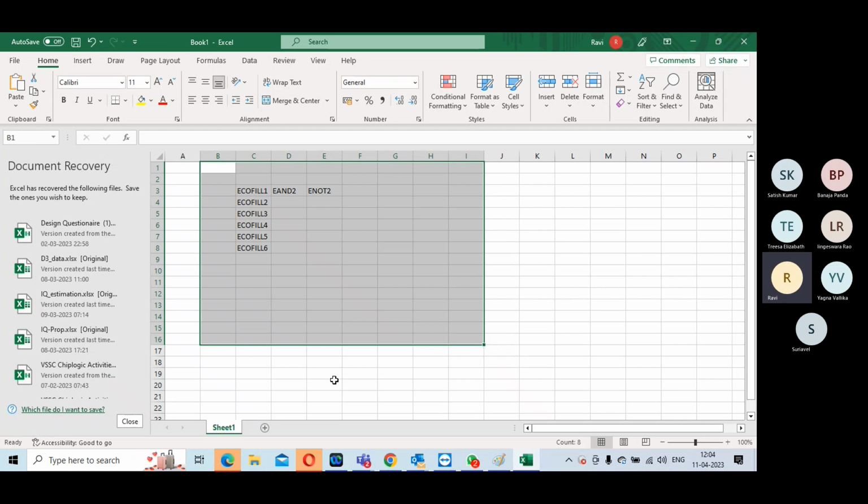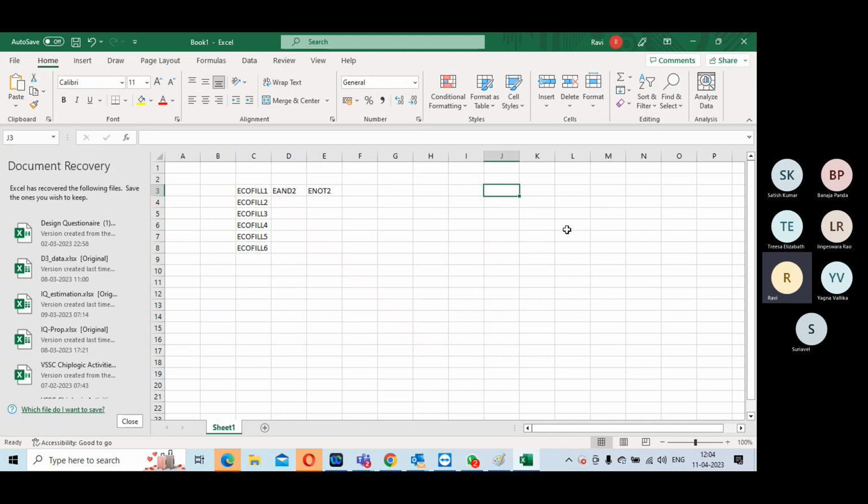The map file, what you are actually understanding as the map file, is different. That is a GDS map file, which tells you what the M1 layer actually means, that it is layer 23 or layer 134. This is the GDS layer map, which you are using in your GDS for your ICC. That is exactly the foundry map, and this stuff is what comes in your map file. But here it is like ECO, which is additional documentation that the foundry will give you.